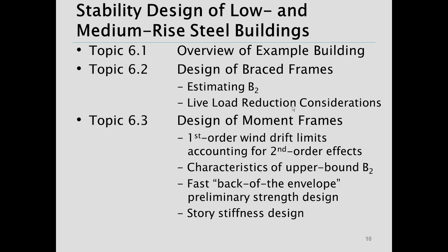We'll talk more generally about characteristics of upper bound side sway amplifiers, B2, some back of the envelope preliminary strength design. A lot of the emphasis tonight is actually on preliminary design type calculations. And we'll wrap up with story stiffness design.